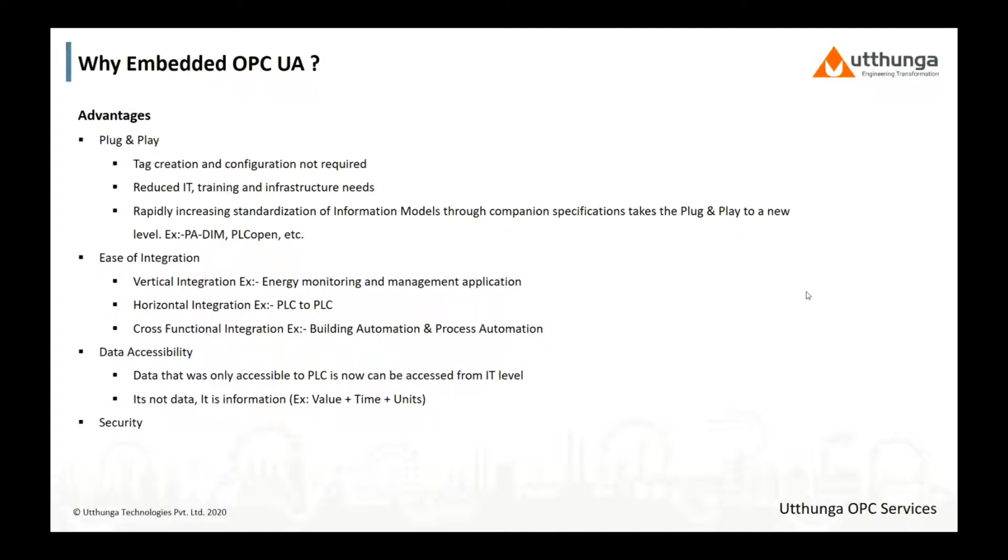But once OPC is supported top to bottom in all the layers, then from any layer, any piece of data can be accessed without jumping through hoops. Also, because it is OPC, you won't get only the value of a particular variable. You will also get the time at which that value was in that variable and what the engineering units were. So you get some context for that value. It's not just data anymore. It becomes information for you.